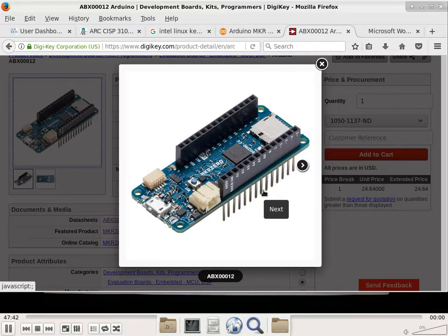So what you do is you tell the compass chipset, start the conversion right now. When you're done, let me know. I'm going to go back and do some more processing somewhere else. So when the compass chipset is all done, it will interrupt the processor and say, hey, you asked me to compute the current heading, I'm done. But that heading may not be in 360 degrees because it doesn't make sense.